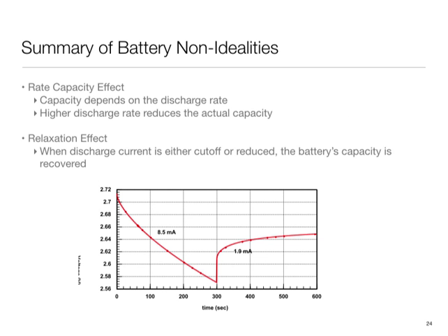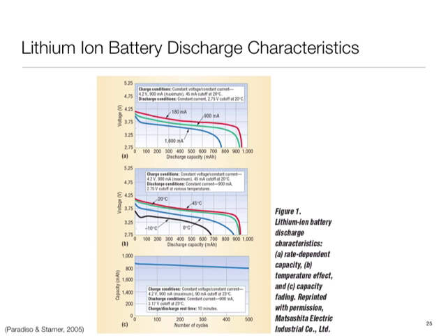So to summarize these battery effects, there are basically two main ones. There is a relationship between the rate at which we are drawing current and the capacity that we see, the rate capacity effect, and the other one is this relaxation or recovery effect. Relaxation or recovery effect is, like I said, not prominent in lithium chemistry, but is there in other chemistries. Rate capacity effect you always see, so in some senses that is the more universal one.